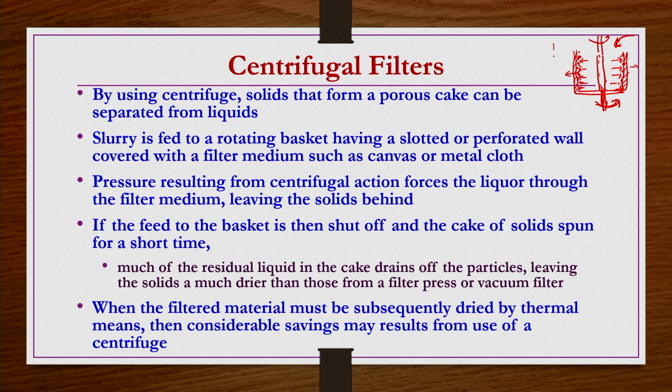So, these kinds of bowls are in general arranged in a kind of casing, something like this. From here, the liquids come out through the wall of the bowls because of the centrifugal action, right. They are in general collected as liquid from the bottom here. Whatever solids are there, provisions are made for removing these solids also in the design. That changes from one design to the other. So, this is the basic principle, right.